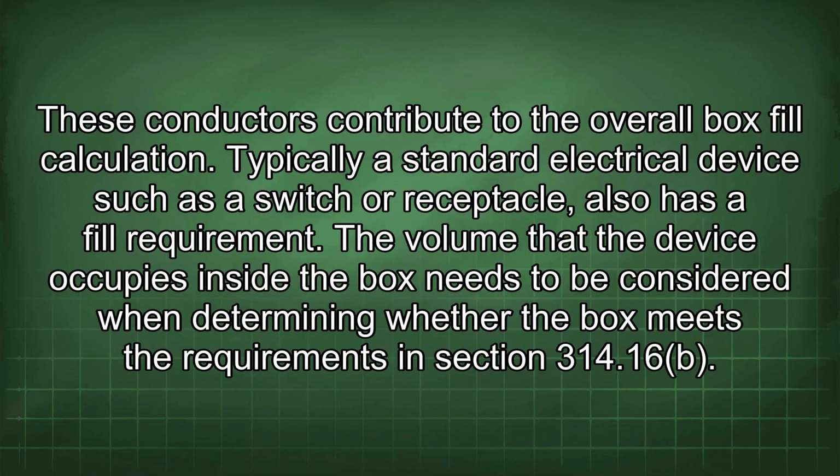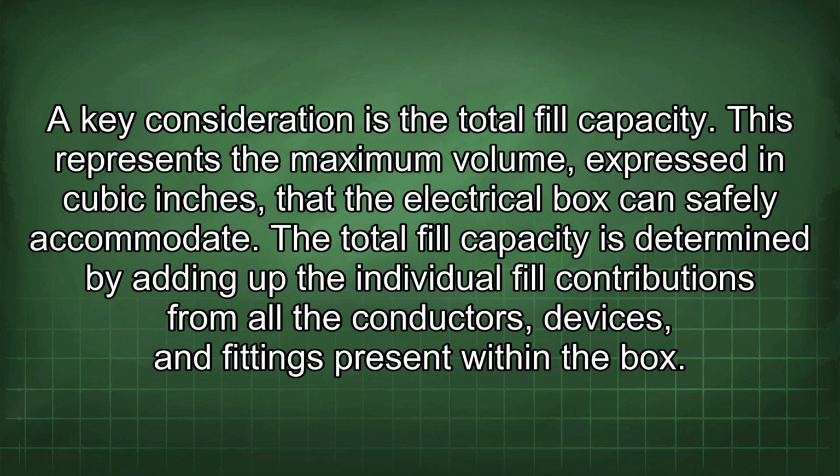The volume that the device occupies inside the box needs to be considered when determining whether the box meets the requirements in Section 314.16. A key consideration is the total fill capacity. This represents the maximum volume, expressed in cubic inches, that the electrical box can safely accommodate. The total fill capacity is determined by adding up the individual fill contributions from all the conductors, devices, and fittings